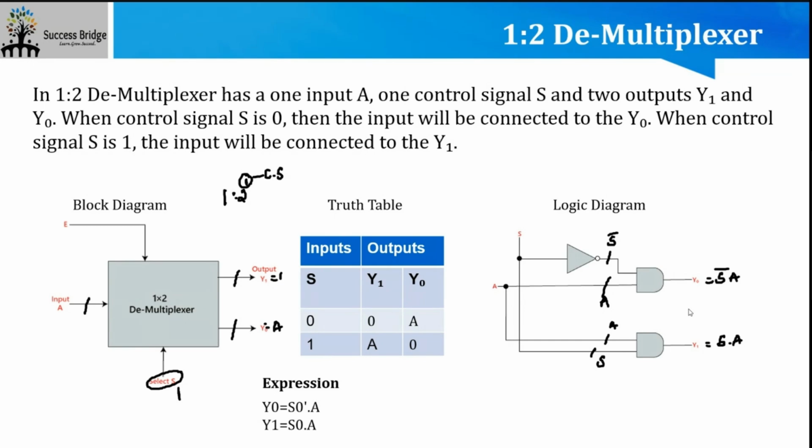So this demux and mux are mostly used in A to D and D to A conversions. Okay, so I mean at a larger scale where you need multiple inputs, let's say 6-bit, 8-bit, 10-bit, 12-bit, 16-bit data, normally we'll go with multiples of 8. So 8-bit or 16-bit or 32-bit or 64-bit. Then you will have a larger multiplexer or demultiplexer as part of your functional logic.